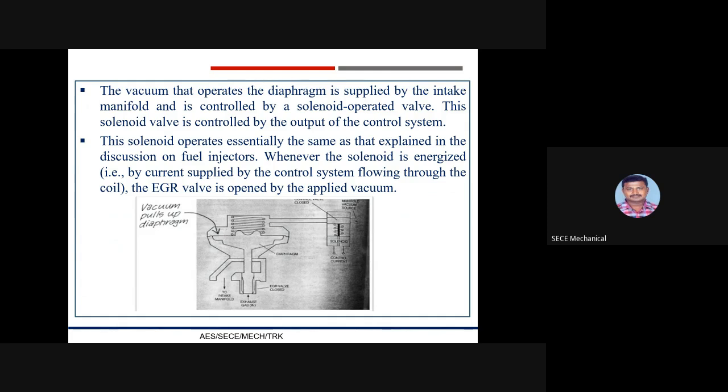So, engine performance issues. One of the first symptoms of a possible problem with the EGR control solenoid is engine performance issues. If the EGR solenoid has any issues, it can cause the finely tuned air fuel ratio to be thrown off, and this may result in decreased power, acceleration, fuel economy, as well as an increase in emissions. Okay, next is engine pings or knocks.